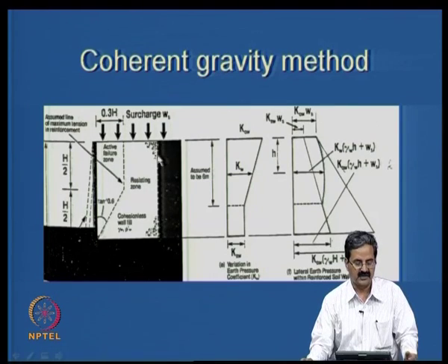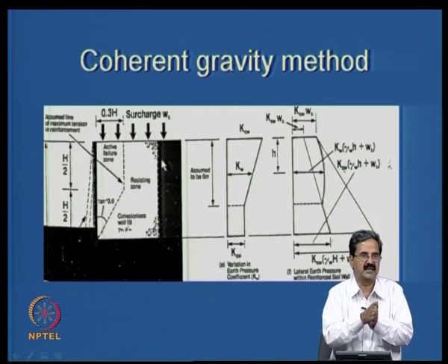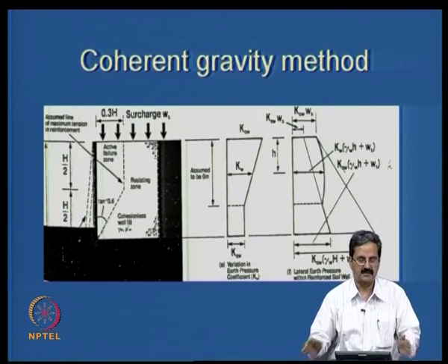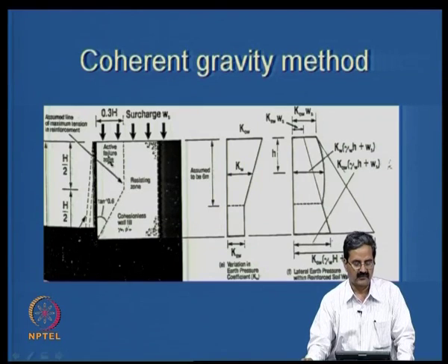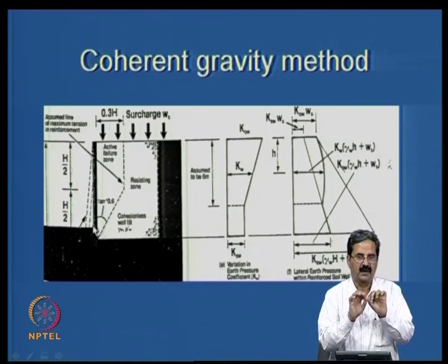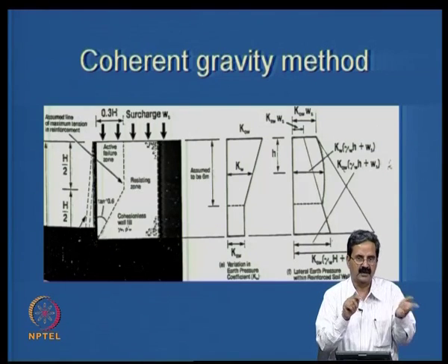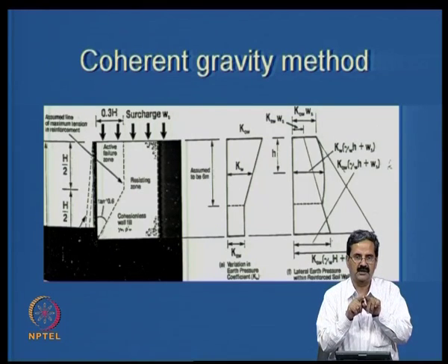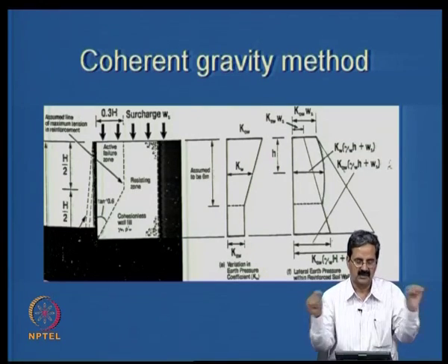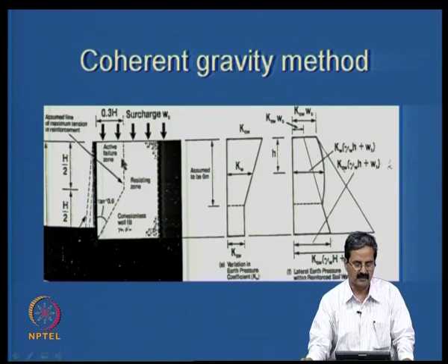Based on that, you get the shear stress distribution along this reinforcement, because this is a shear stress mobilization, right? Shear stress mobilization along the reinforcement. Based on that, you can locate this actual failure surface, because beyond this point the shear strain distribution will be different on either side. So that's what it means.